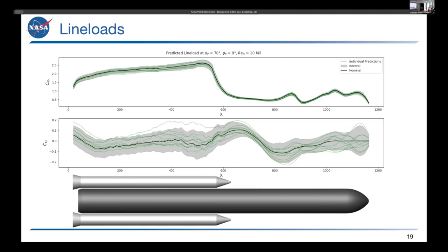One thing that we really like about this method versus our naive increment-based approaches we've been using previously is that we are crossing the nominal here as we go through. Because one of the concerns is when you're doing this sort of loading analysis being used with these line loads, you're not just necessarily worried about the integrated forces, but also the shear stresses. So being able to change the slope implicitly changes the shear stresses that will be captured in any downstream analysis. So really happy with that.